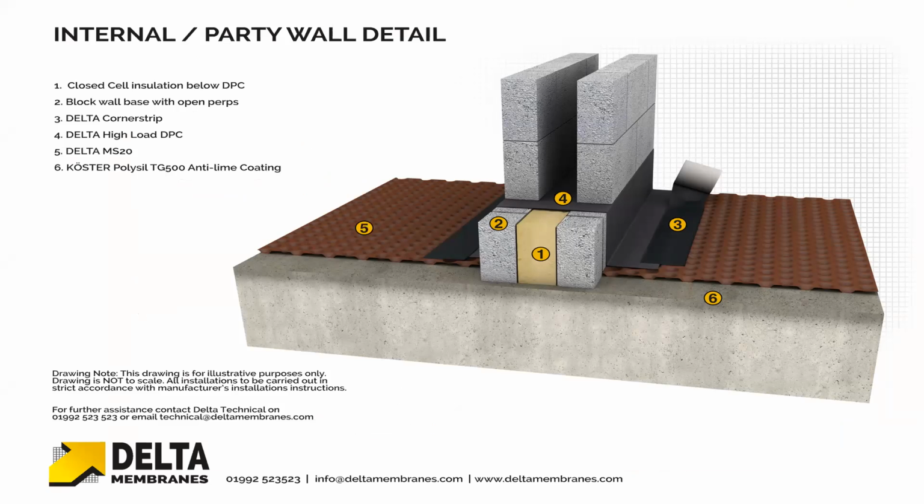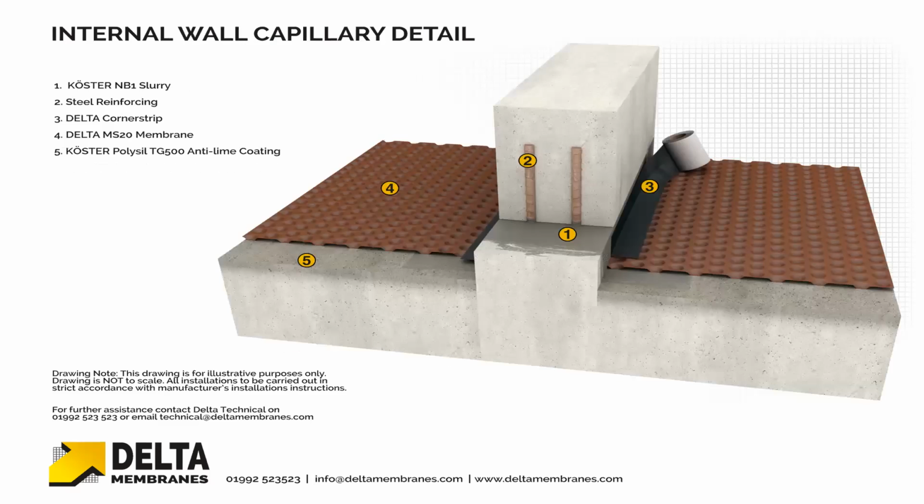So how do we manage internal load-bearing walls with Type C systems? Well, the internal cavity drainage membranes need to stop and start, don't they? Because we don't build structural walls on cavity drainage membranes as a rule. So we have the internal wall transferring its load straight down to the slab, and we have what we call weep holes or mouse runs in the wall so that water can get from one side of the wall to the other, through the membrane, through the wall, and access the drainage channel, wherever that might be. We simply connect the membranes through the wall using a wide profile damp course, which is taken over the lower block there. So that's continuity of a Type C system through an internal load-bearing wall.